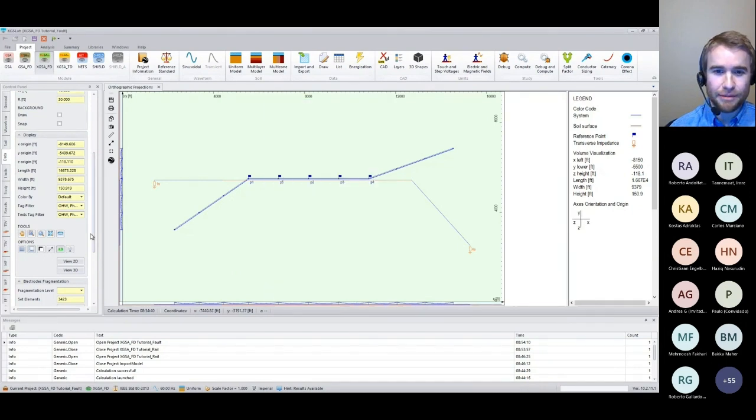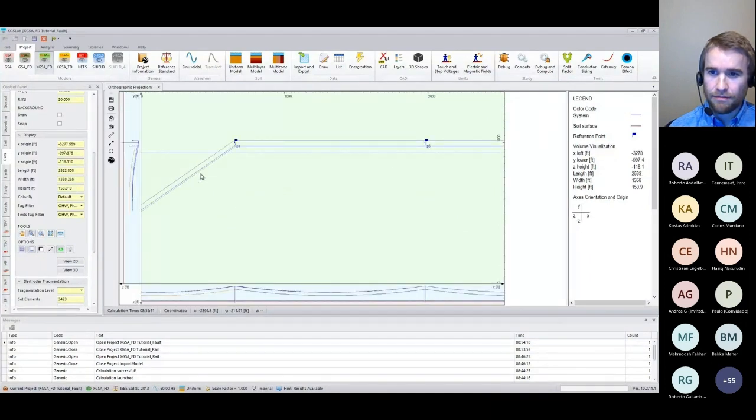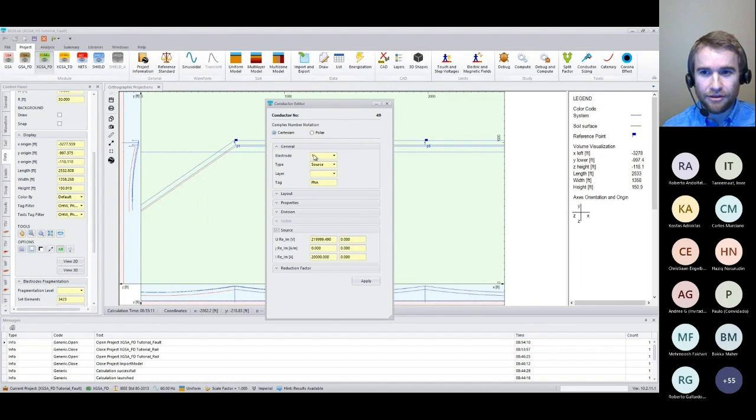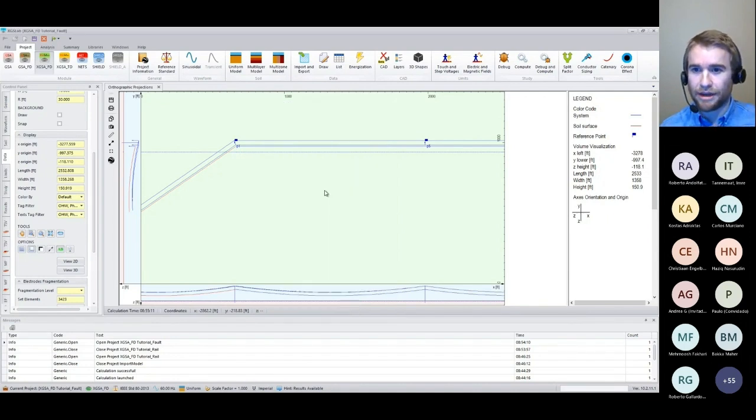What I'm concerned about is a fault through the corridor, which is simply if I were to take my phase conductor, so zoom in right here, and we just change that source from 1,500 or 1,000 amps to 20,000 amps, well, then we can account for the induced voltages that occur from that transmission line phase conductor to that pipeline that's magnetically induced, electromagnetically induced.